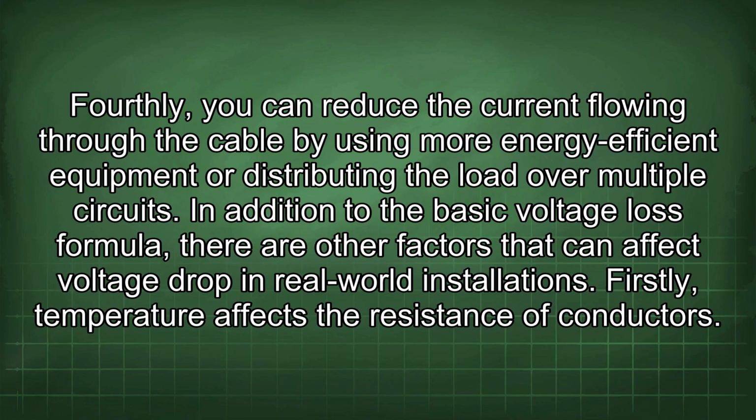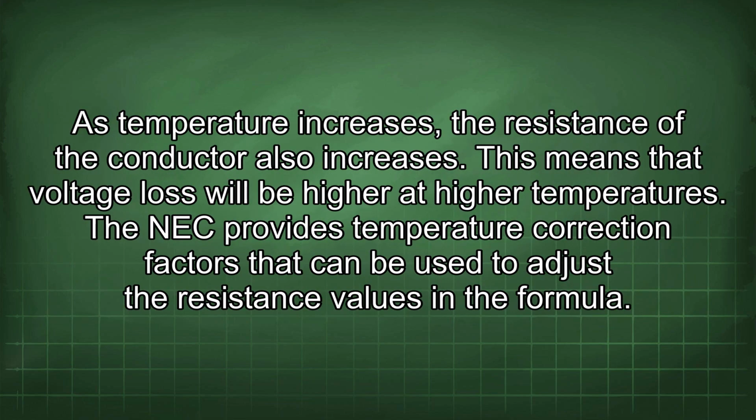In addition to the basic voltage loss formula, there are other factors that can affect voltage drop in real-world installations. Firstly, temperature affects the resistance of conductors. As temperature increases, the resistance of the conductor also increases. This means that voltage loss will be higher at higher temperatures. The NEC provides temperature correction factors that can be used to adjust the resistance values in the formula.